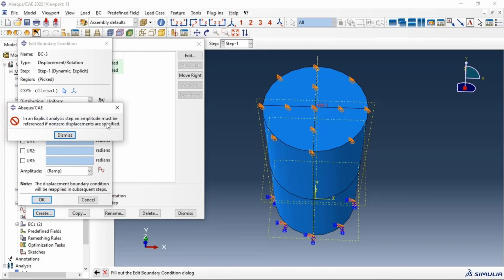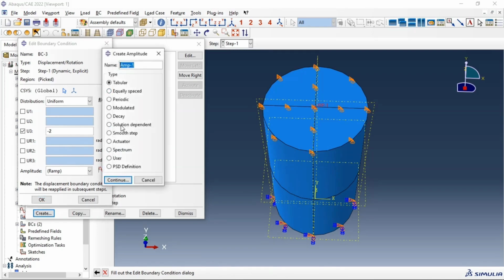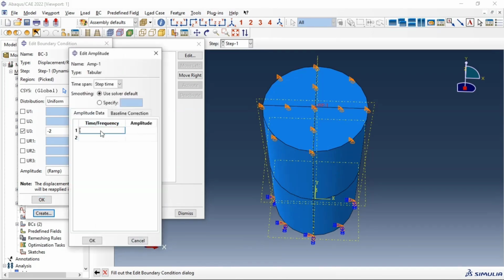Together, the four data sets, that is tension damage, tension stiffening, compression damage, and compression hardening, collectively allow the CDP model to accurately represent the cracking, crushing, and irreversible damage.